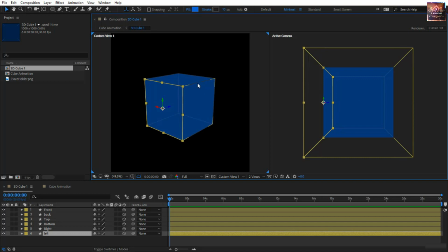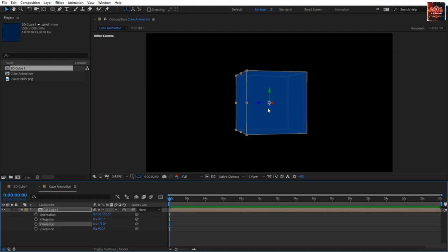So actually, if you can imagine it, the flat composition is in the middle of the cube. Hence, when you come and put it in 3D, the anchor point will be totally in the middle of the cube. This is a concept that somehow is confusing. Try to create some other shapes that are 3D and then bring them in, and try always to get the anchor point in their middle. That will be quite good.